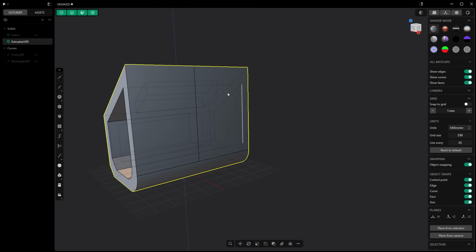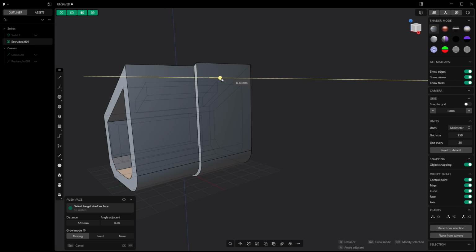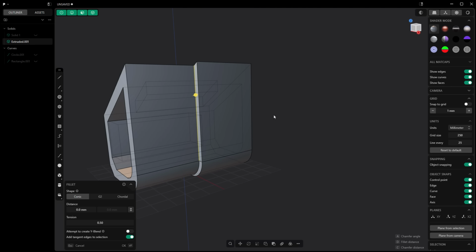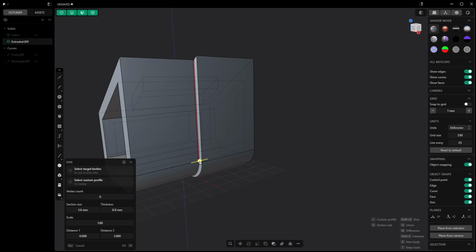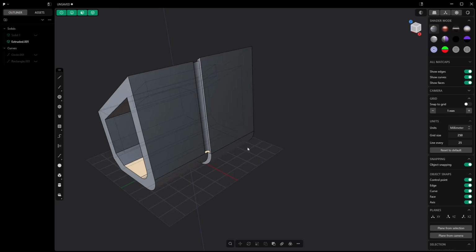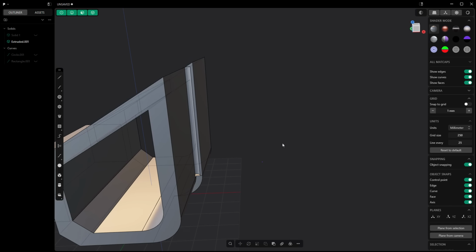So this allows me to create a division here, and I can either pull this geometry out and offset it if I want. We can also use these edges for tools like the pipe tool. Pipe tool is P on the keyboard. You can also find it in other places. That allows us to create like a recess cut in there.